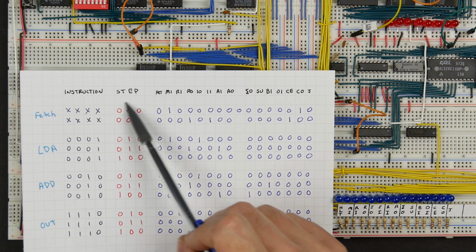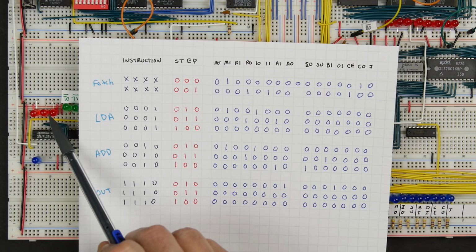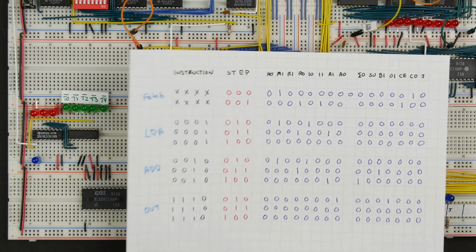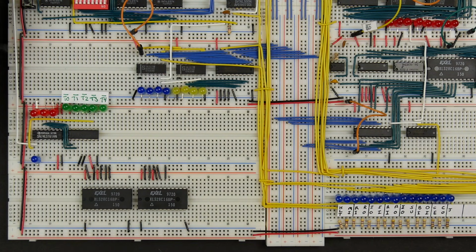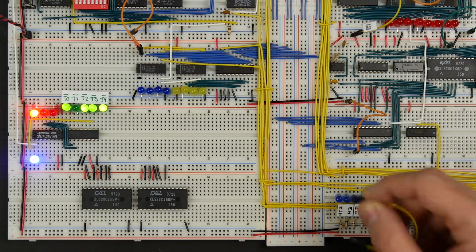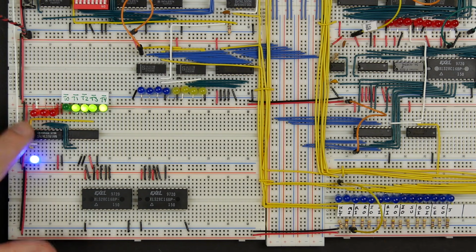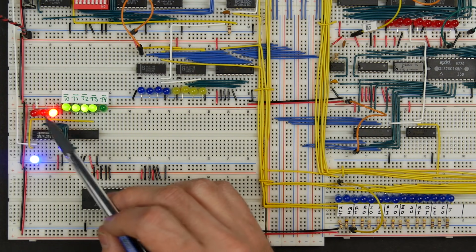So let me first hook up the step, those 3 bits, which are basically these 3 bits here that count which step we're on. Let me hook those up to the first 3 address lines. So let me just figure out which of these, I forget which of these 3 is the least significant bit, so which one should be address 0. So let me just double check. We add power. See, the clock's not running, probably because we're halted. So if I connect our halt signal, because I've disconnected that, if I connect that back to ground, there we go. So clock's running.